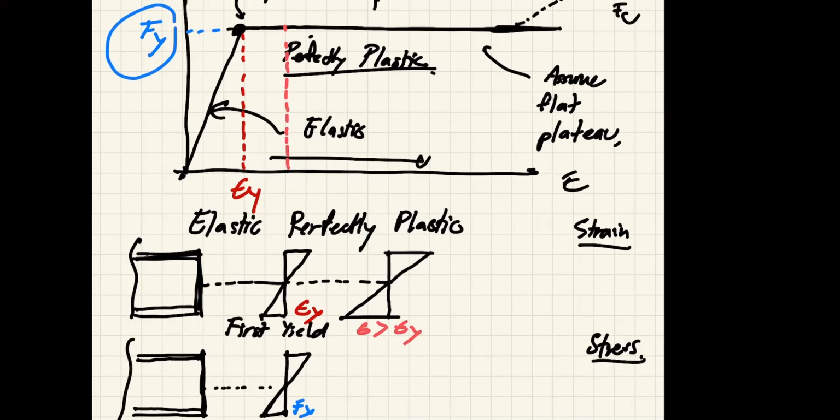If you look at the strain, because I use one block, you can see very clearly that this is perhaps where you have the strain equal to yield strain, correct? So what will happen to stress at the location beyond yield strain? You cannot go beyond Fy, right? Because we use this model.